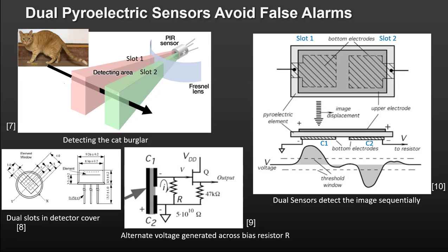When spurious signals due to mechanical stress are applied to both sensing elements simultaneously, they are canceled at the input of the electronic circuit. Because the infrared energy focused by the Fresnel lens is absorbed by only one element at a time, the cancellation is avoided. Thus, only the infrared energy is used to detect presence of the object, not the spurious signals.